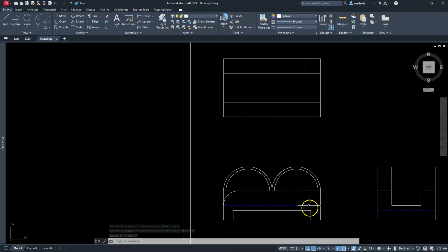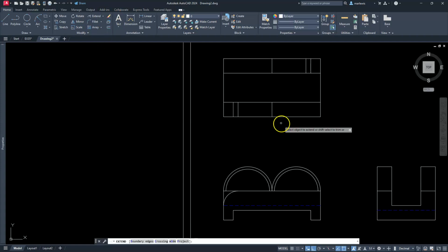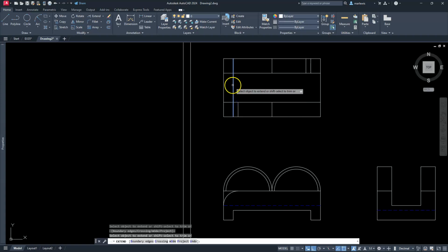Here along the top, I can track these up here, or I can just do an offset. It's just an offset of 10. Remember that we offset this number at 15. So I will go back to offset, type in 5, enter. I'll offset both of these lines here. And then I'll go to the extend. So extend is just EX, or you can just come here and select extend. And then we're going to extend both of these inside lines.